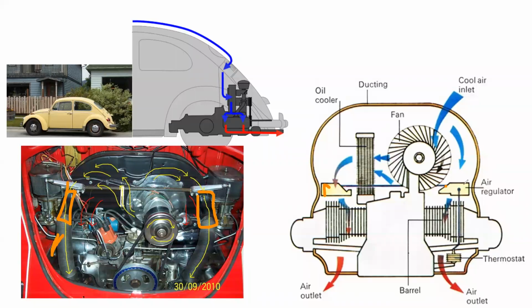When this valve or door is fully open, air passes around the cylinders, cooling them. But when the vehicle is going faster, or if the temperature around it is low, these valves will be fully closed, and there will not be any airflow around it until it comes to the operating temperature. Once it reaches the operating temperature, it opens again and sends the airflow around it.